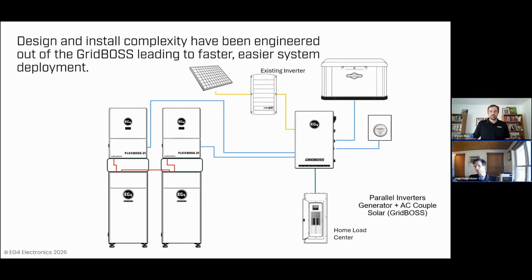So our existing solar is going to land into our smart port. Our generator is going to land on our dedicated generator port with its 2-wire control. Our grid ports, dedicated. Our load output, dedicated. And then we have 2 hybrid inverters landing on their dedicated hybrid inverter ports.